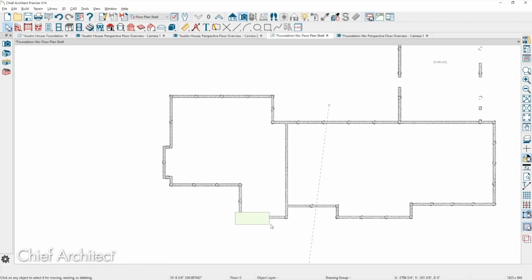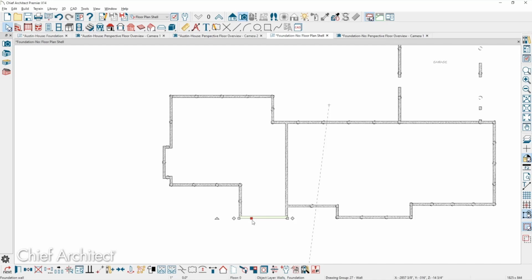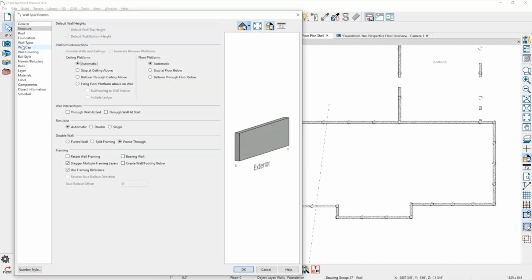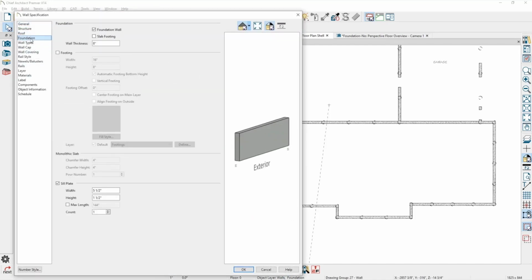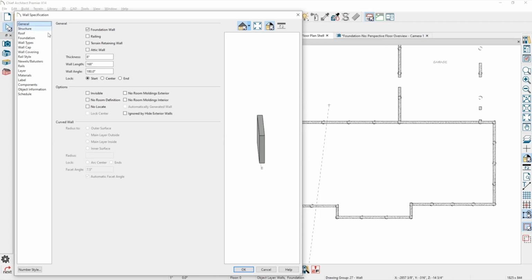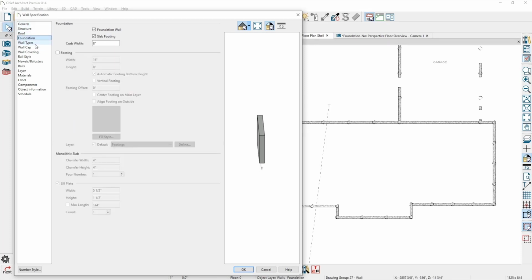The way you delete those piers off of them, just highlight them, delete them, right? And then those would remove the piers off of there. And then you can change this wall, or all of the walls that are appropriate on the foundation. You could put a slab footing on it. And let's see what wall height thickness is. Go back there and put the footing on there, and then you've got your footing set up that way. Does that work for you?